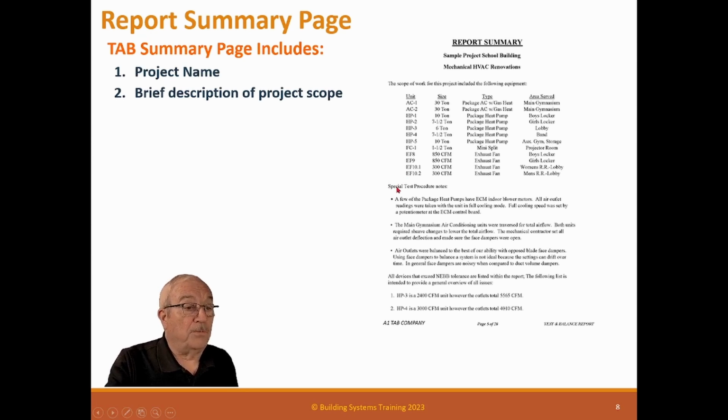The reason this is important in a remodel job, let's say you have a building with a big air handler and you're only testing half the rooms on that air handler. Well, there's a problem there, because you really need to set up the air handler itself, even though it's serving part of the existing building. We would normally just pitot the existing part and then reset it up so that the pitot is the same in our new part. But you understand that you have to do that air handler, so you need to expose what you're doing and what you're not doing.